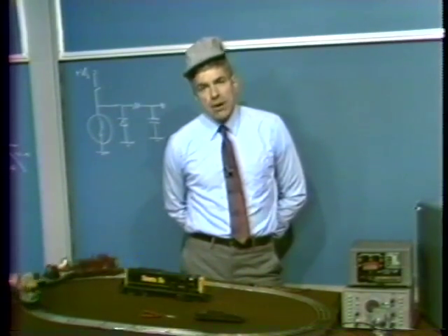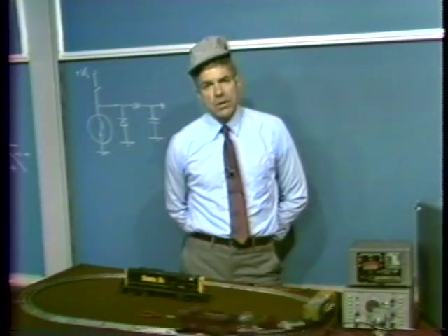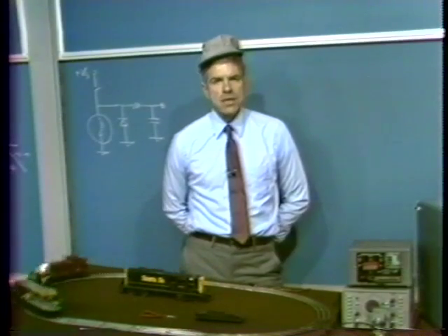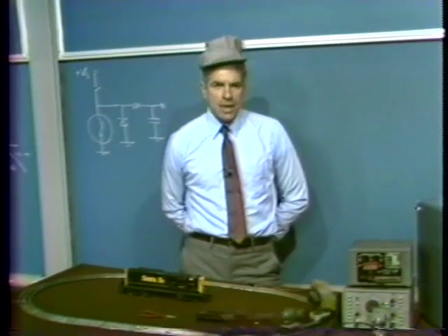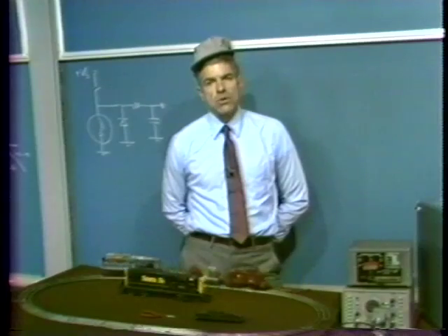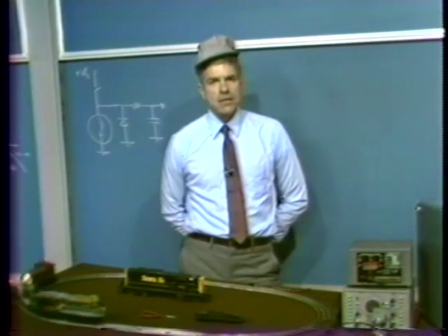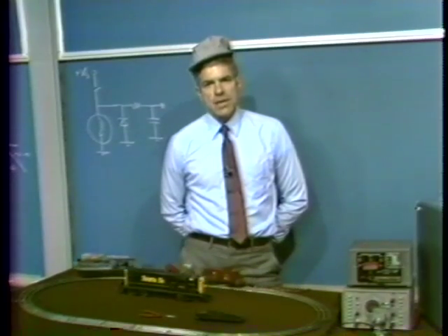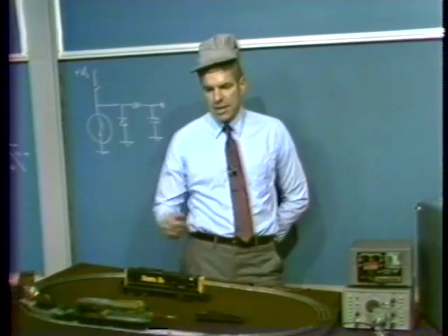If the output voltage is half the supply voltage, you're putting an equal amount of power into the control element and into the motor in this case. And if we had to be able to get 20 watts or so into our load, we'd be dissipating that kind of power in the controller. Well, that's unacceptable. You just have trouble getting 20 watts worth of heat sink on an engine like this.